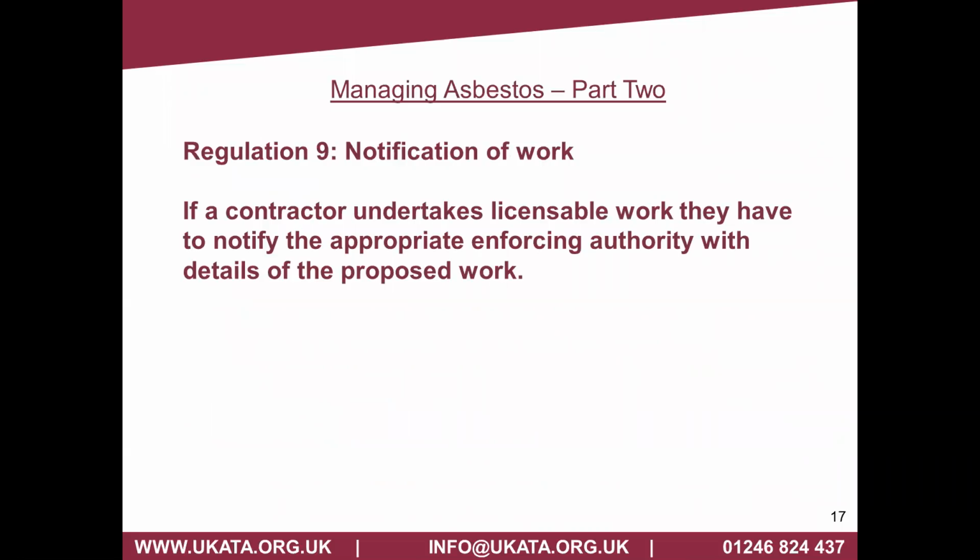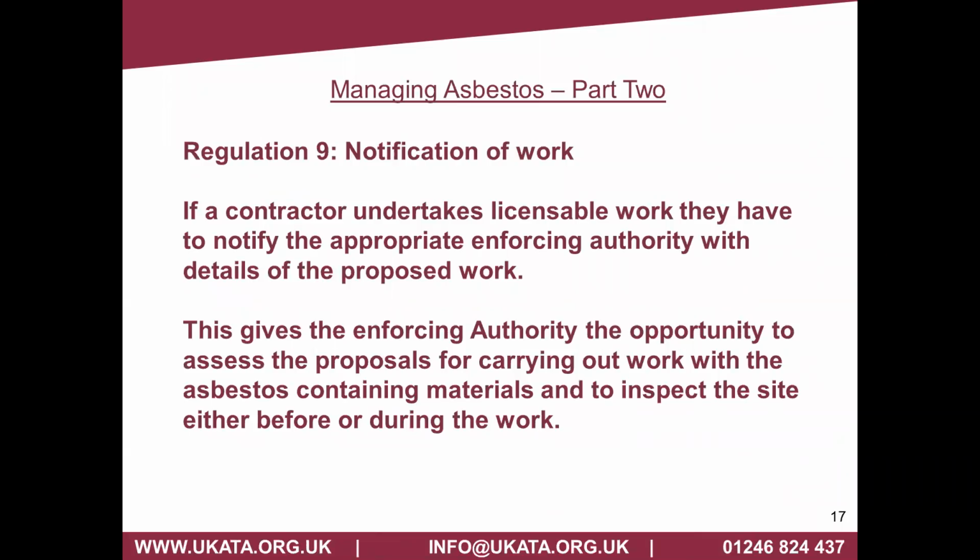That notification obviously has to be submitted before 14 days of the works commencing. It could be submitted longer than that, that's fine, but it certainly has to be within the 14 days. This gives the enforcement authority the opportunity to assess the proposals, and they may request additional information, but the ASB 5 is the only form that is submitted to the HSE.